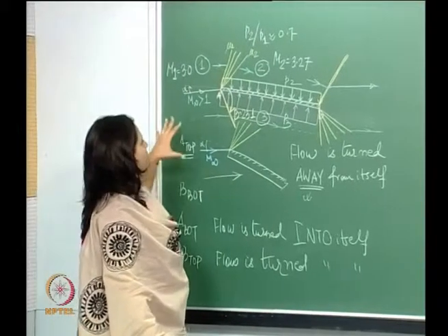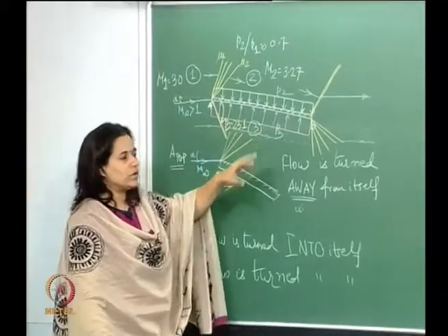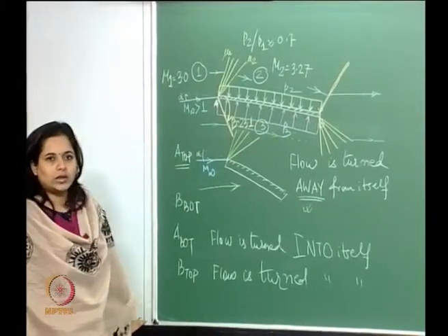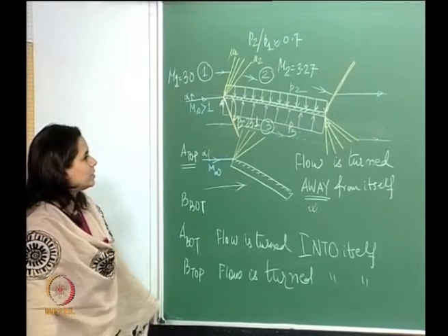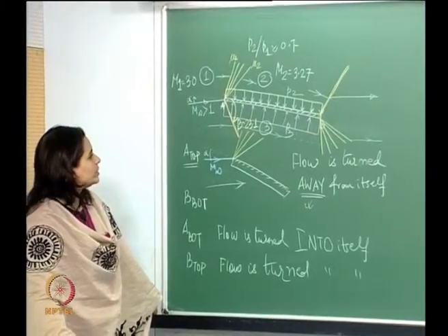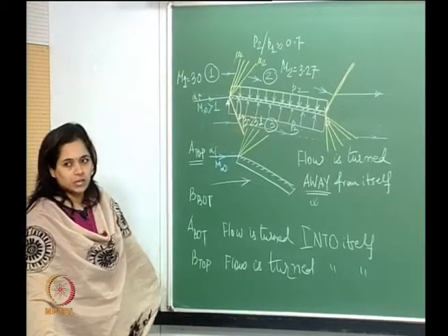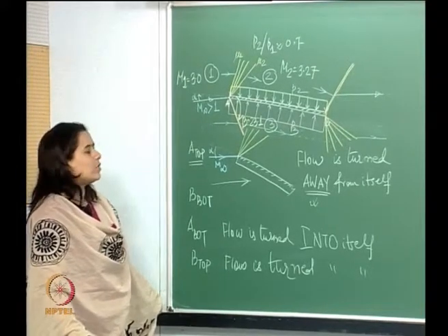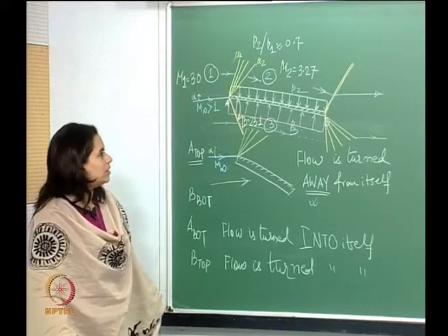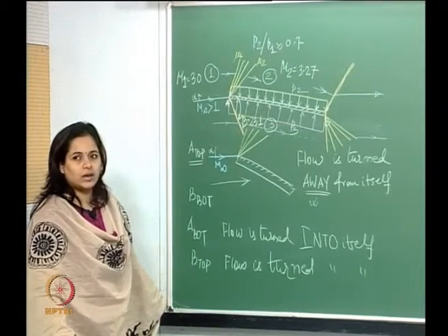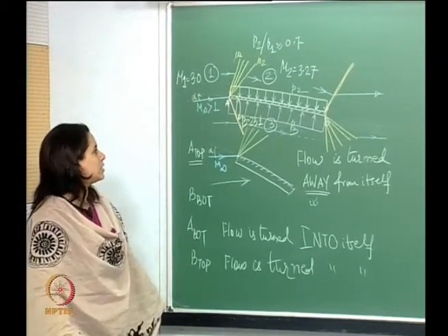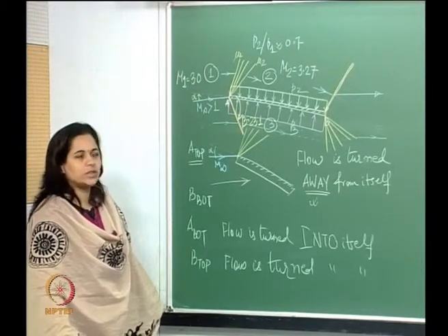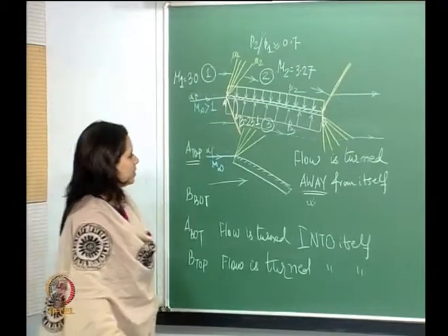But what is interesting is how we are able to apply it here, and calculate or study properties across surfaces, which are basically made up of straight elements. Like we saw yesterday, we had more than one surface attached to each other, and we were able to use our knowledge of shocks and expansion fans to calculate the coefficients of lift and drag across them as well.